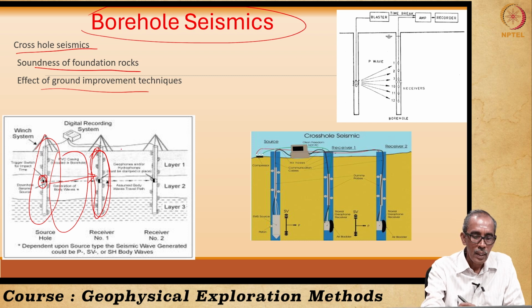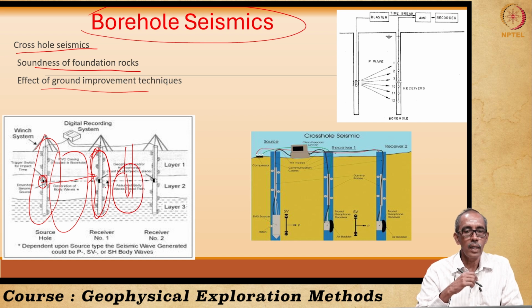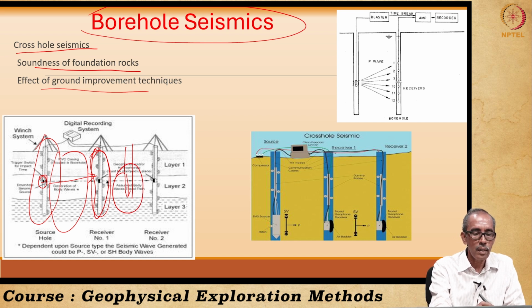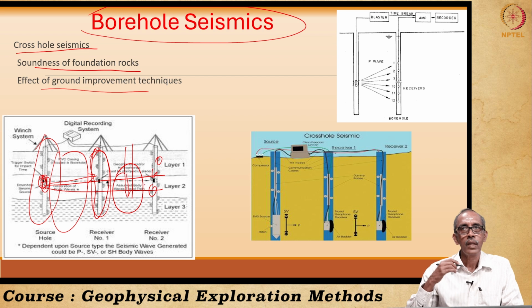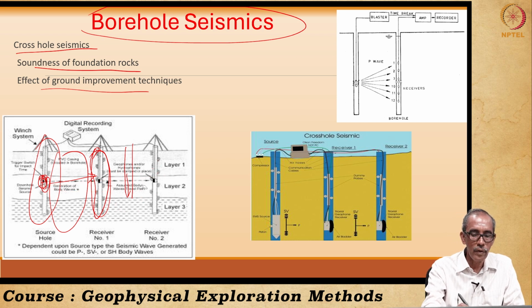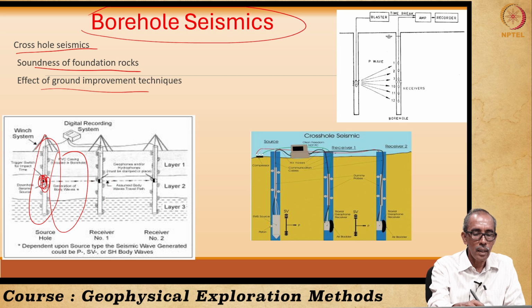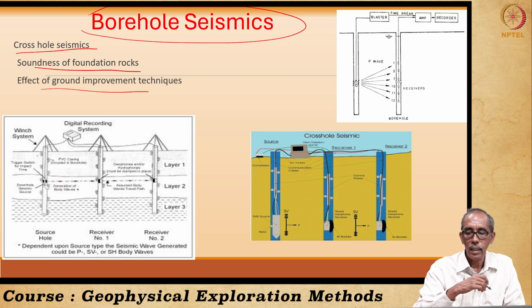For example, if we have done grouting in the borehole here, how effectively we have done the grouting can also be estimated by firing a shot or generating a shock. The shock waves travel through the formation and are sensed by the geophones here. So, this is how we can deduce how we have improved the ground by the grouting method.